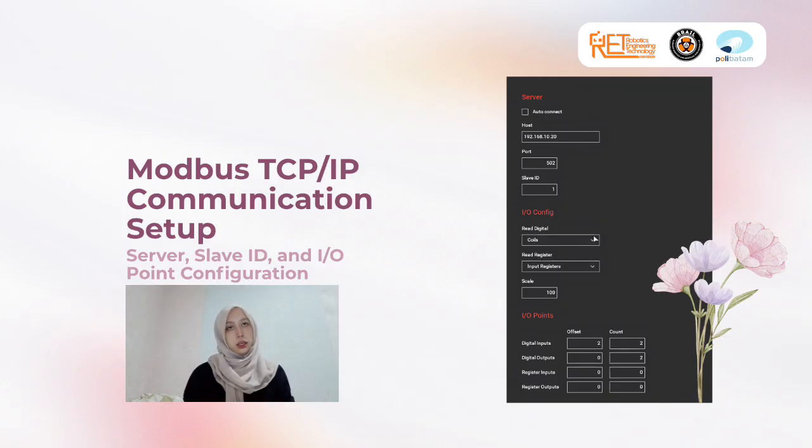And then there are the digital inputs, where the offset is set as 2 and count set as 2 also. This is the range for the two sensors, which are add entry and add exit, placed right after the outputs, starting at coil 2, since I have two output coils before it.